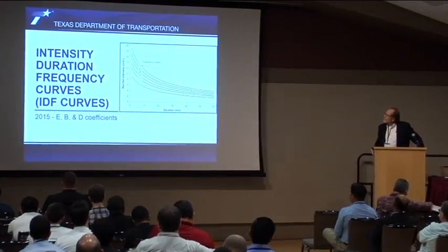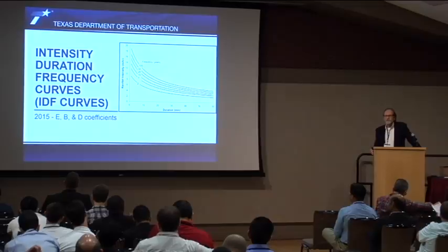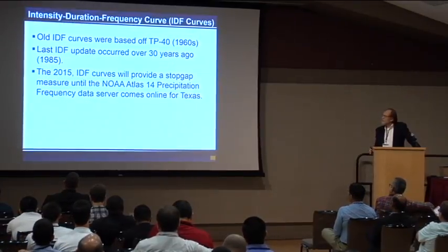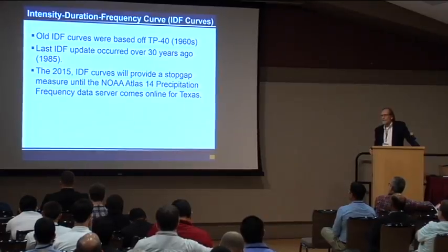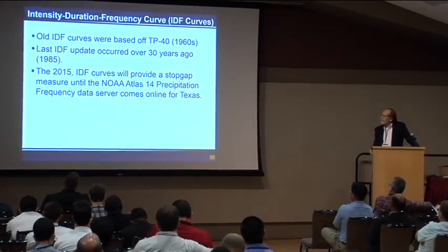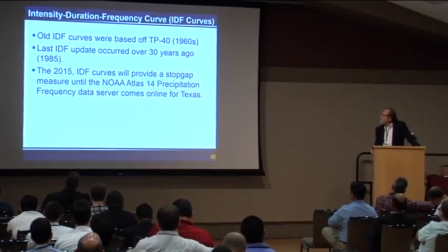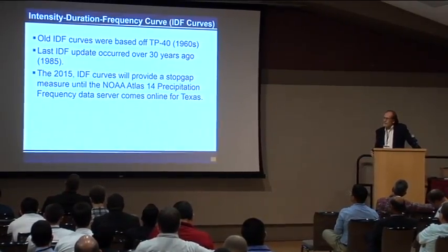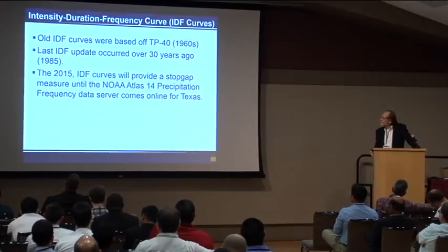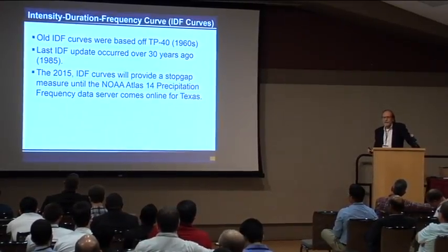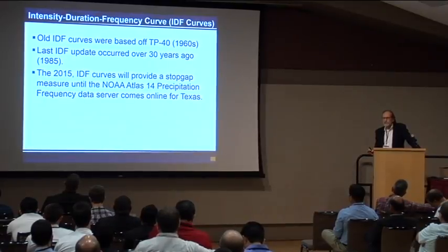The next update I want to talk about is the IDF curves. They've recently been updated. They were actually based off of TP40, the original ones. And last update was almost 30 years ago, so it's been some time since our last update. The new curves, 2015 IDF curves, are going to be kind of a stopgap until the NOAA 14 Atlas comes online, and we'll talk about that a little later here.